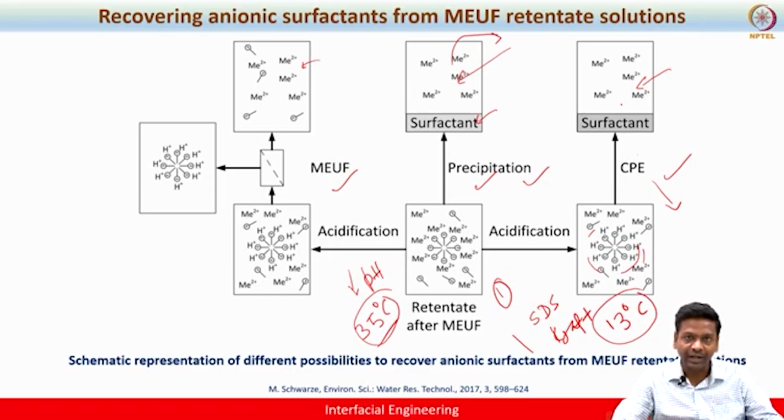In this way, it is easy for us to separate the surfactant from the cationic impurities, and this surfactant can be reutilized for the treatment of wastewater containing pharmaceutical and healthcare products. The same strategy can also be used for the micellar-enhanced process.